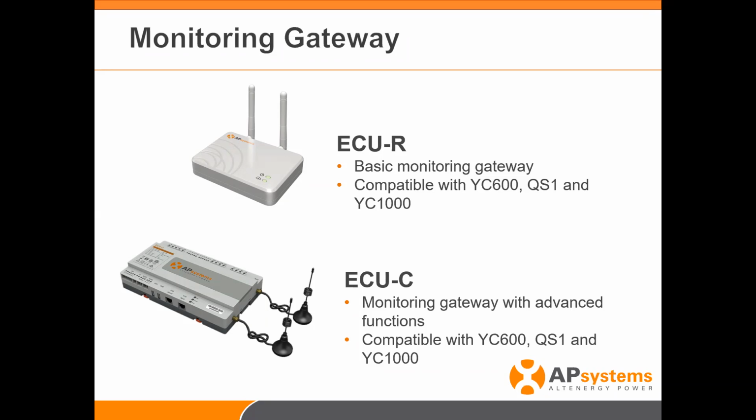They won't produce any power without AC, of course, but they will communicate. So you'll have a visual indicator when you make that first connection, that red dot followed by 3 greens, you'll see that on the roof. And then in your ECU app, you'll be able to see that there's communication between the ECU and the inverters. All of that happens without internet. All of that happens without AC.